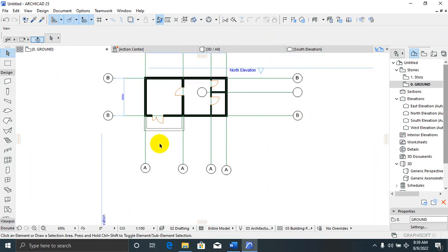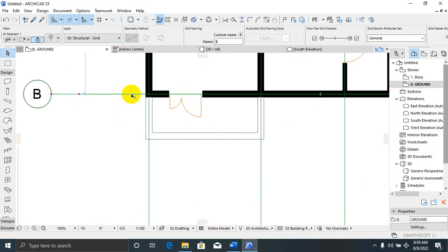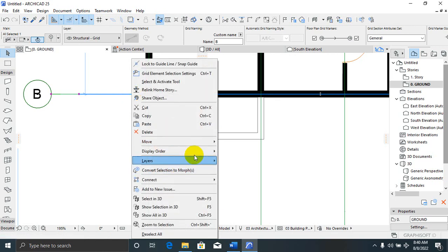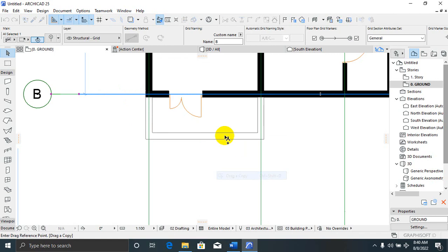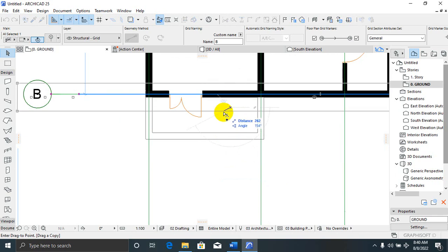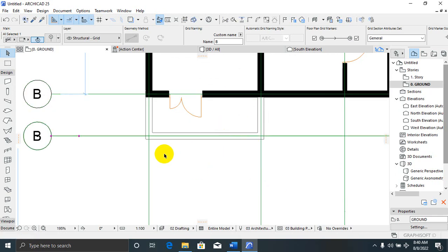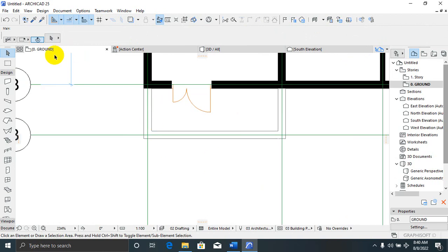So if I have this now, let's say I now want to have my railings here, at, if you punch in your calculator, okay, it's at the center. So I'll copy, drag and copy at 1500. Oh, this is not straight. 1500, and I'll click on enter. Good. Now it's at the center, so I can draw my rails here.